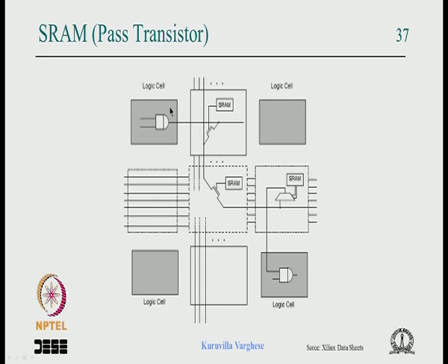This shows an FPGA architecture with, say, 4 configurable logic blocks, horizontal wires, vertical wires, and a switch interconnecting the vertical wires, and this shows that the output of a logic cell is connected to the vertical wire. So the connection is an NMOS transistor, pass A0, and basically if this N transistor is on, the output is connected to this input, and similarly this vertical wire has a connection to the horizontal wire using an N transistor. So if the gate is made high, it connects.